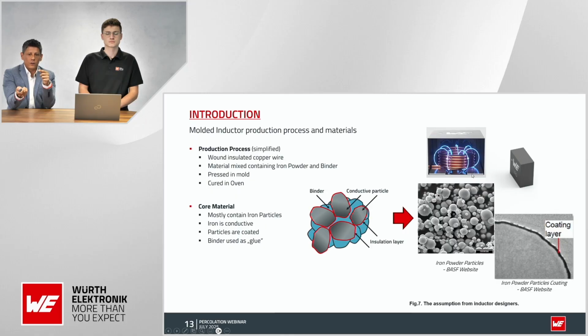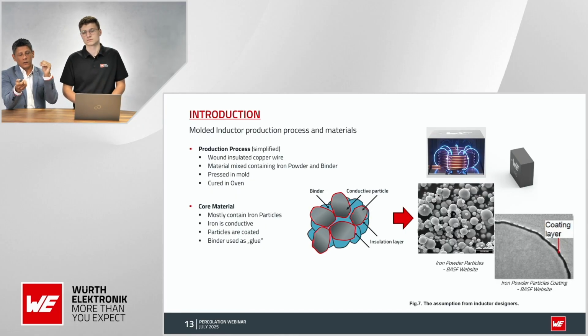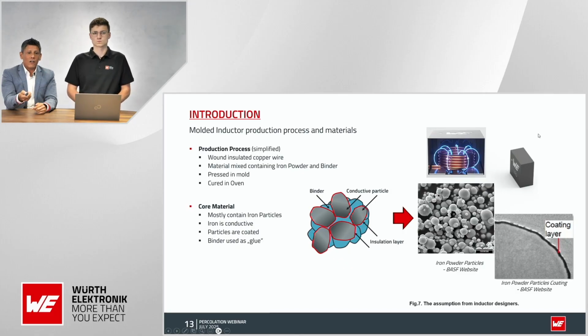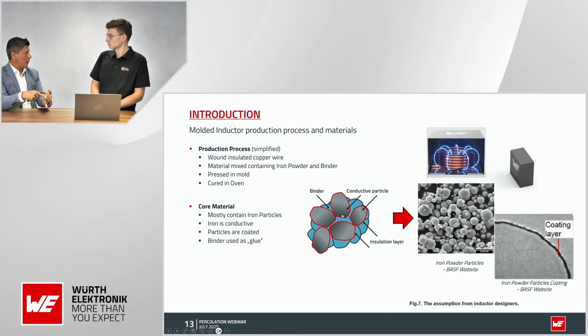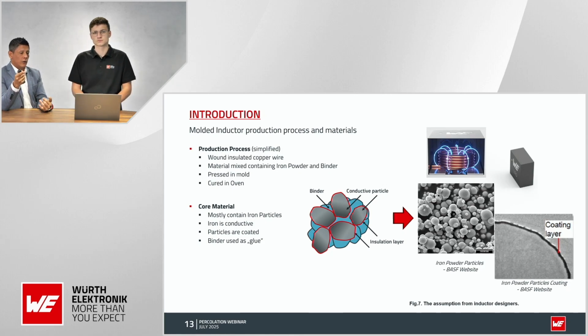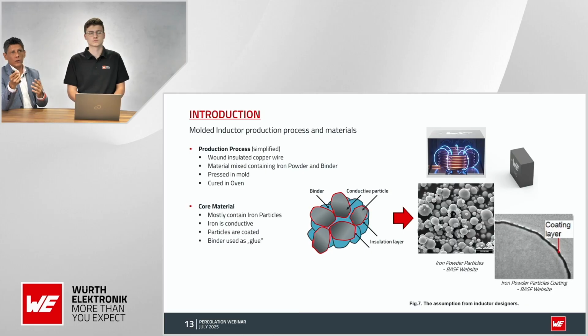And more important in this case is, for example, some competitors see the problem and allow the use of non-organic coating materials, but then they offer you a range for one size of only 3-4 inductance values, because you cannot play around with the benefits of molded inductors and materials to offer smaller or bigger inductance values, because the size is too small. So you really need this kind of advantage of the concept itself of molded.